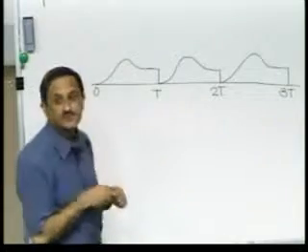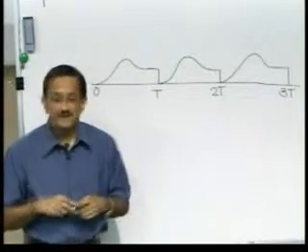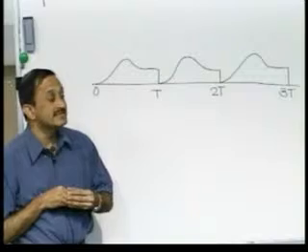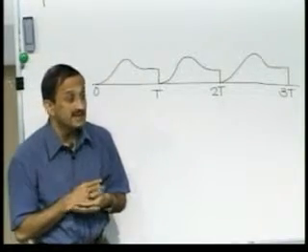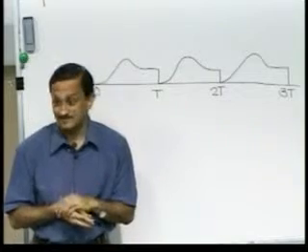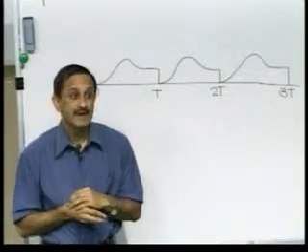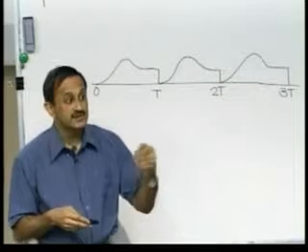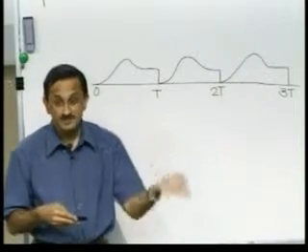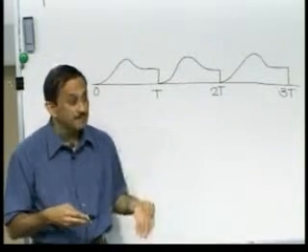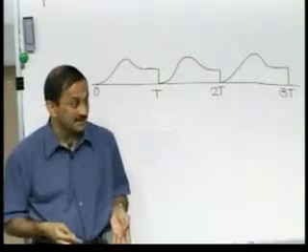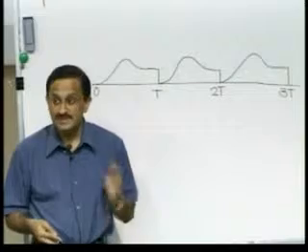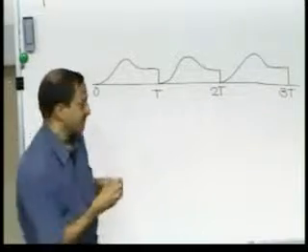Anyway, coming back to this, let us assume first that we could use an ideal interpolator, in which case we could take samples of this. But naturally, if we were to obey the Nyquist principle, then our samples should be taken at more than twice the frequency that this waveform has, which is inordinately large. So, from the frying pan into the fire: where we try to display fast waveforms, we are now asking for a sampler that can sample at even higher than the frequency being actually displayed. So, that would not work. So, instead, let us do the following.